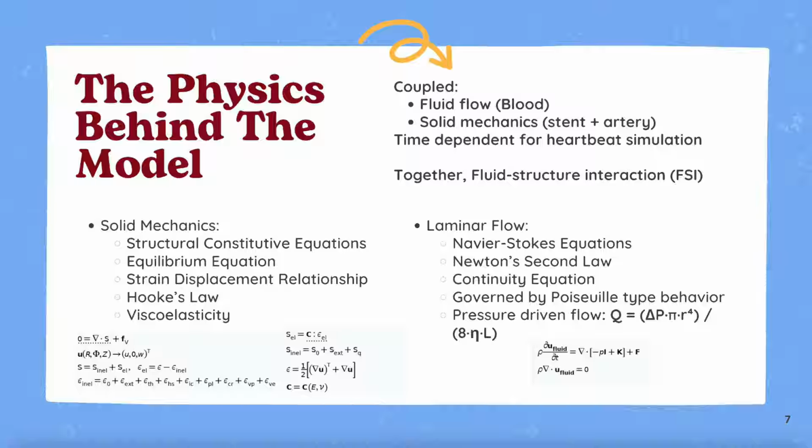We used the time-dependent blood pressure function in our inlet condition to simulate pulsatile flow, hence mimicking the effect of a heartbeat. Finally, the multiphysics was applied, allowing the two types of physics to interact and have effect on one another, with pressure from the blood deforming the artery wall and stent. In taking this approach, we would be able to model and understand the coupled behavior of fluid and structure, increasing our knowledge of how stents behave in real physiological conditions.